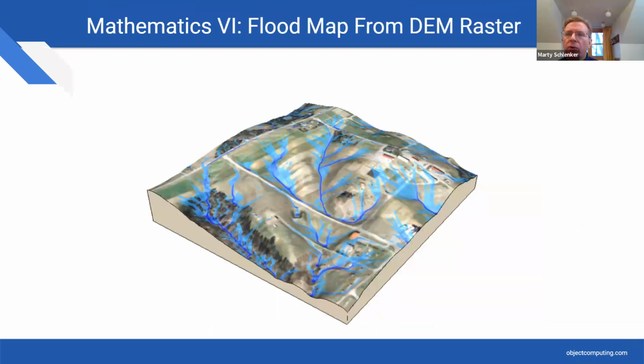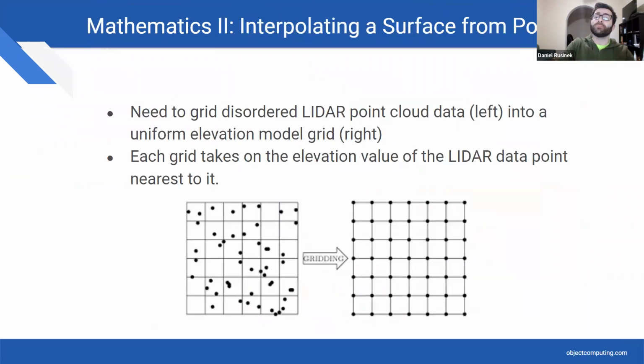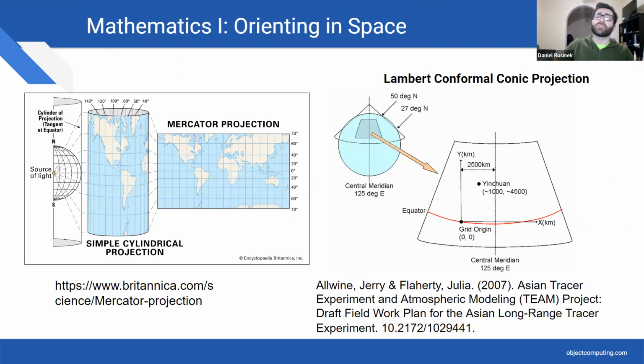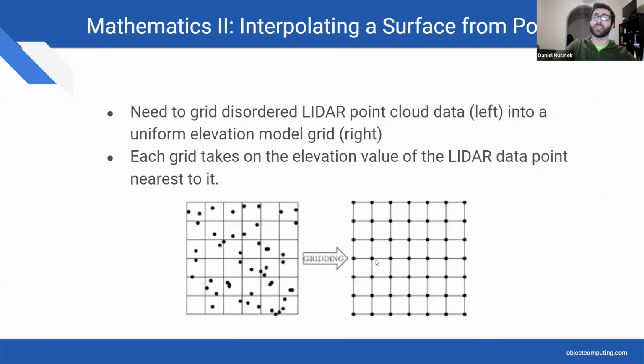And Daniel, that was where northing and easting came in. Oh, yes, going back to that, I need to mention it. When things are done in any kind of projected coordinate system, you have a point at the edge of, let's say you're in Georgia, the edge of your zone, and every point you get is really relative to that point. So it's a certain amount of feet east of this point and a certain amount of feet north of that point. That's what we mean by northing and easting.